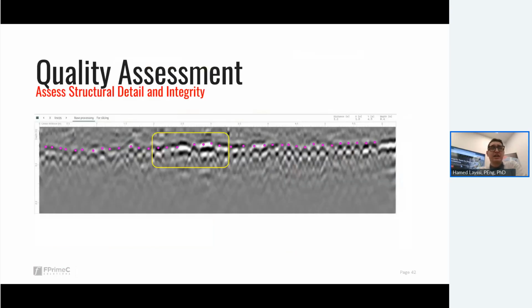We did GPR on many lines here. Assessment of the GPR scans showed some signs of GPR anomalies. It's very difficult to characterize the anomalies in this graph, especially in the view that you have here. But towards the right side, there is a sign of early stage delamination, and this part at the center appears to be delamination on top of the steel reinforcement. So we can't prove it right away through GPR.